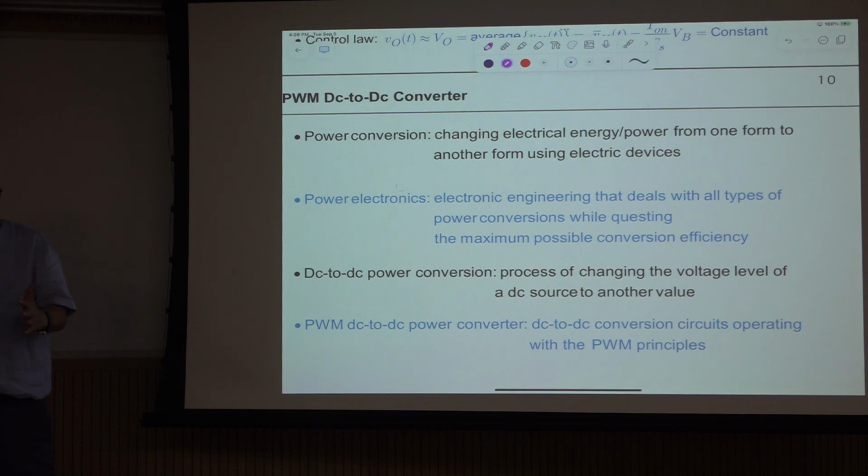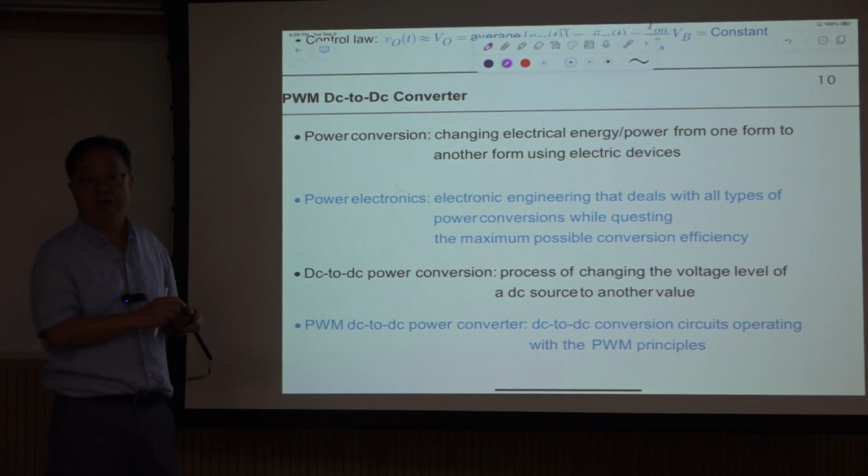Then we need switching. We are doing switching to reduce the power loss. Otherwise it increases the power loss dramatically and becomes useless. So the previous alternative solution using an SPDT switch and low pass filter is a good example of power electronics, but the resistive solution is not classified so, because there is huge power loss.